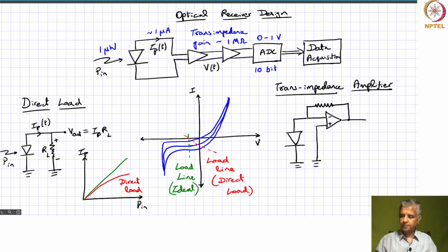If you connect it to the positive, there is a possibility of the circuit becoming unstable and basically becoming an oscillator with positive feedback. So we typically prefer the negative feedback configuration for something like this.